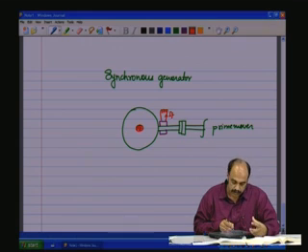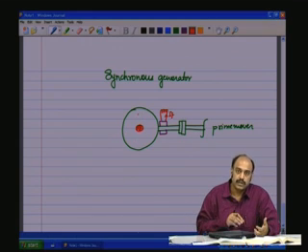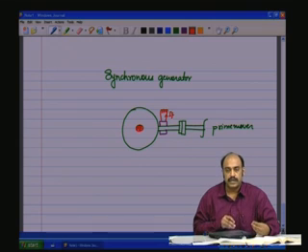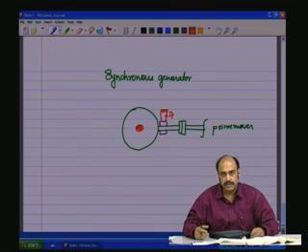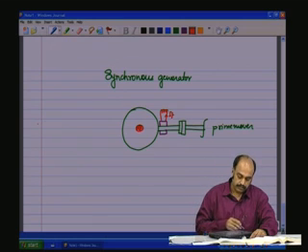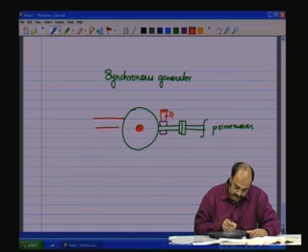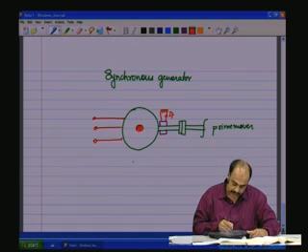So the rotor becomes a permanent magnet, and that is rotating, and because it is rotating, it is inducing the voltage on the stator coils by Faraday's principle, which is N dφ by dt, and that is being used to supply the electrical loads on the stator side, the three-phase electrical loads. And under such conditions, this is called the alternator.